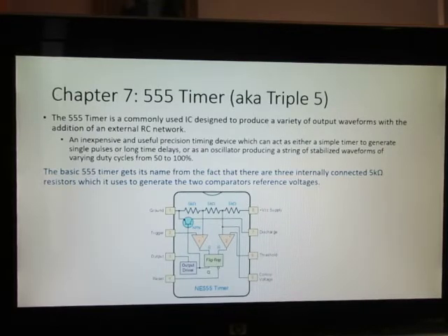So when you're introducing the 555 IC, it has a number of useful functions. It provides a variety of outputs that we'll be discussing. And the name 555 comes from these three 5K ohm resistors that are in the circuit, internal within the 555. And really, by the way, there are around 28 transistors internal. What we're showing here is just a functional block diagram inside that 555.